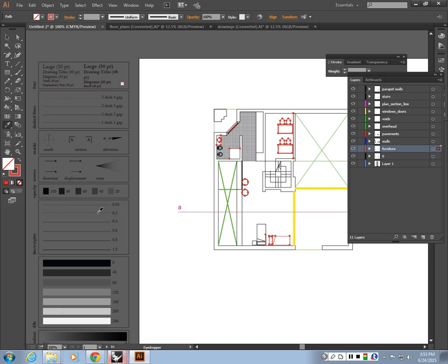And then furniture, it needs to be thicker than the pavement. So it's going to be 0.4. I click here. My furniture is updated. What else? We have windows and doors. They're going to be thicker than furniture. Eyedropper tool, 0.8. Okay. Overhead, eyedropper, 0.2. And this one is voids, so I can click on this one. I can make them 0.2 as well.